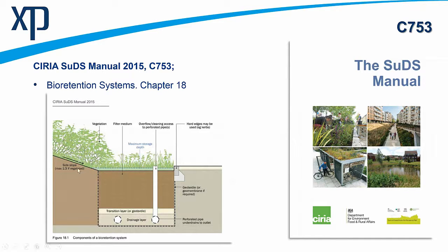They would typically be no steeper than 1 in 3, maybe 1 in 4 on the side slope. Vegetate the depression. The depressions are often fairly shallow, but can be deeper, and there is no one-size-fits-all with this. Below that depression area, you have this shallow ponding effect.